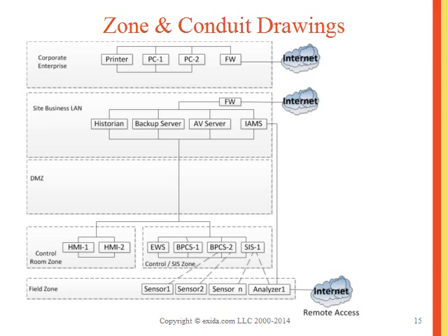Now, this could very well be a typical installation. However, the first thing that would obviously be of serious concern is what appears to be a direct internet connection to your field. This is certainly not a good practice. Likewise, the demilitarized zone, the DMZ there, seems to have no components in it, and with a wire going straight from the business LAN into your controller. So obviously this is not an optimal drawing here, but could very well represent a particular installation for someone who hasn't paid attention to or had any particular security-related concern.